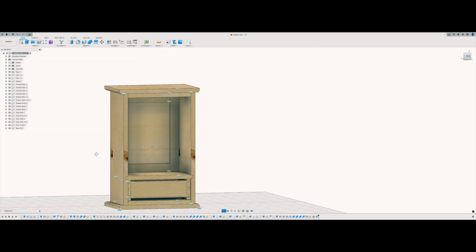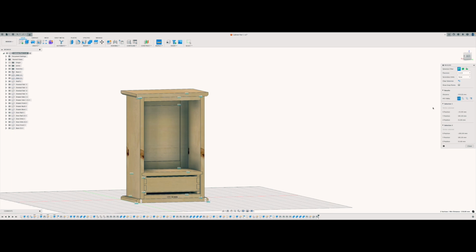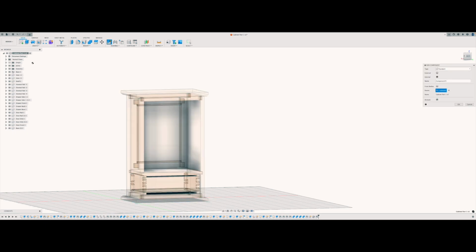So for our back panel, I reckon we just draw a panel that goes all the way over. So let's do some inspecting here. I'm going to measure from this corner to this corner, which is 250. Press escape. Same again. We're going to go from here to here, which is 400. So we need a back panel. So new component, back panel.